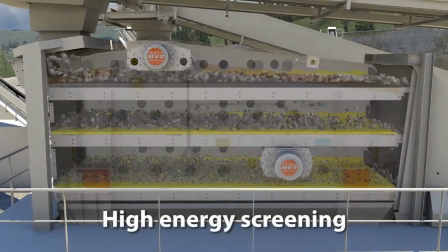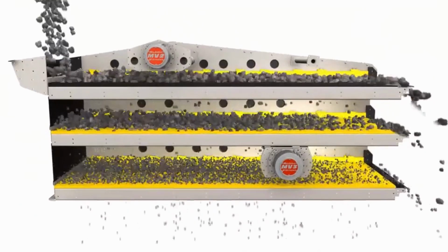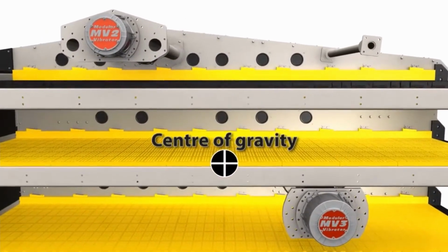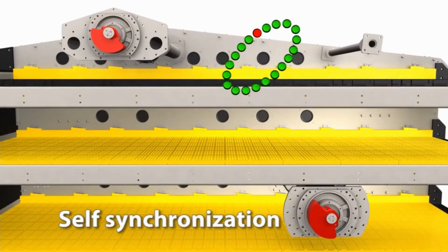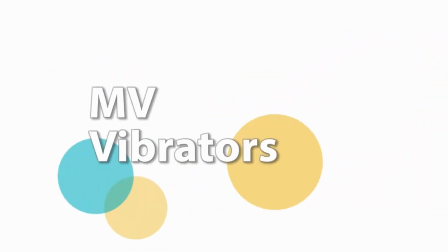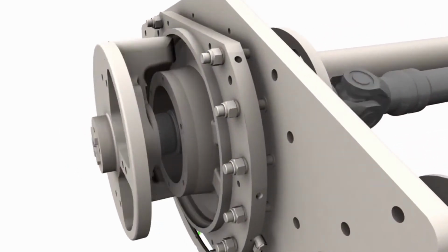And this video is quite nice because they're going to show you guys some different elements, starting with the screening. So here you can see 3 decks screening. So the first deck is the upper deck. We tackle the coarse particles, then the middle ones, you call this middlings, and then the fine particles. And the motion is elliptical. It has to be elliptical. And the center of gravity in every good screening has to be in the middle of it. Okay, so it has a system called self-synchronization, that if the 2 weights come off, they just synchronize themselves. Okay, and then you have the maximum of the screening that you can have.